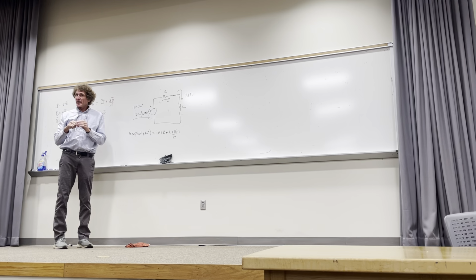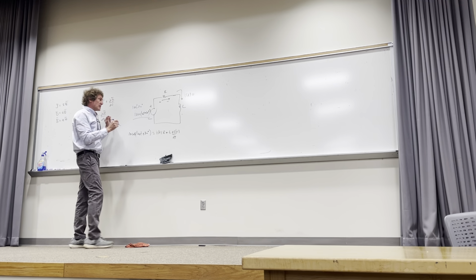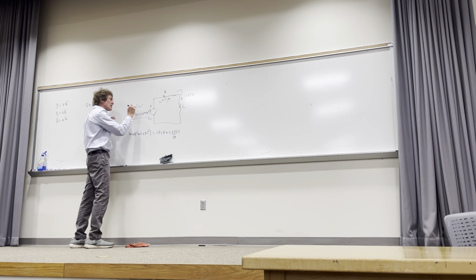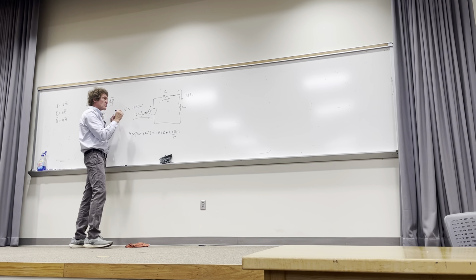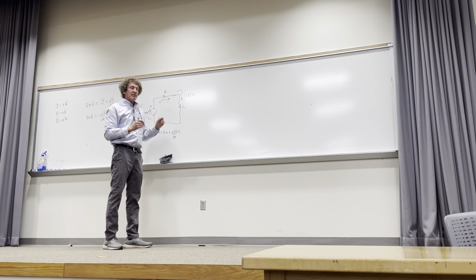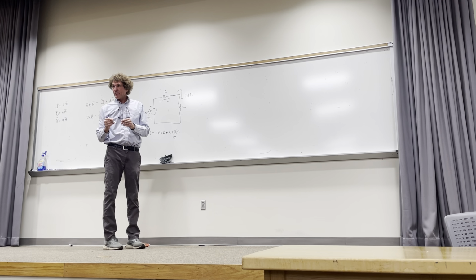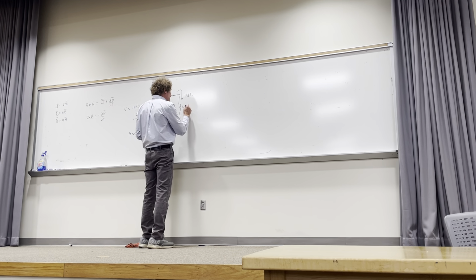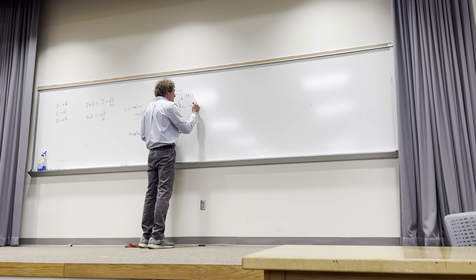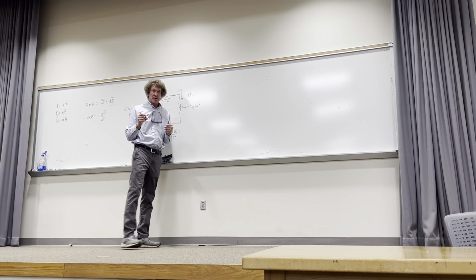Now we're getting rid of the actual cosine variation. We know it's varying like this. We know everything's varying at that frequency. We make this 10 at an angle of 30 degrees as the voltage source. And then instead of having L there, we put inductive reactance there. Y'all remember that? Now this would become simply j omega naught L as an impedance, correct?